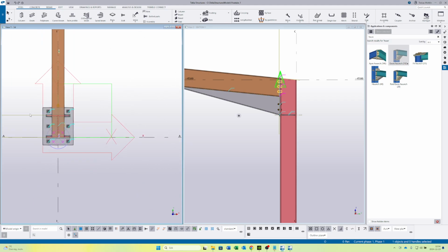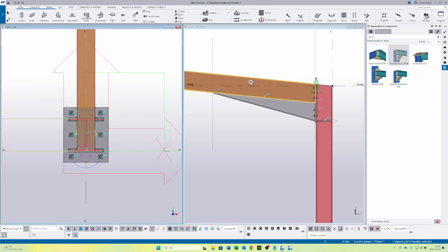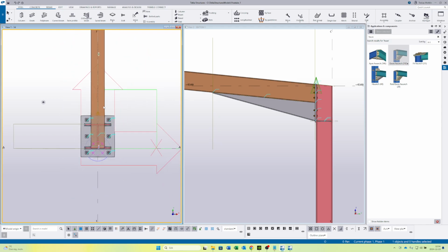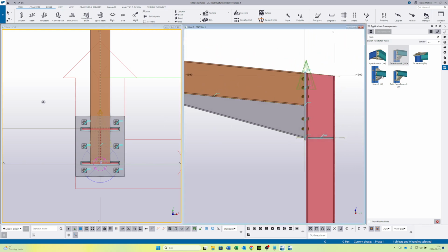Now the profile that Tekla adds on your eaves haunch will be the same profile as the rafter above it. And that's kind of cool because that's usually how you do it actually. You will notice later that the same is not true for the apex haunch. So you will have to manually adjust that. But one thing at a time. Let's go back into our eaves haunch.